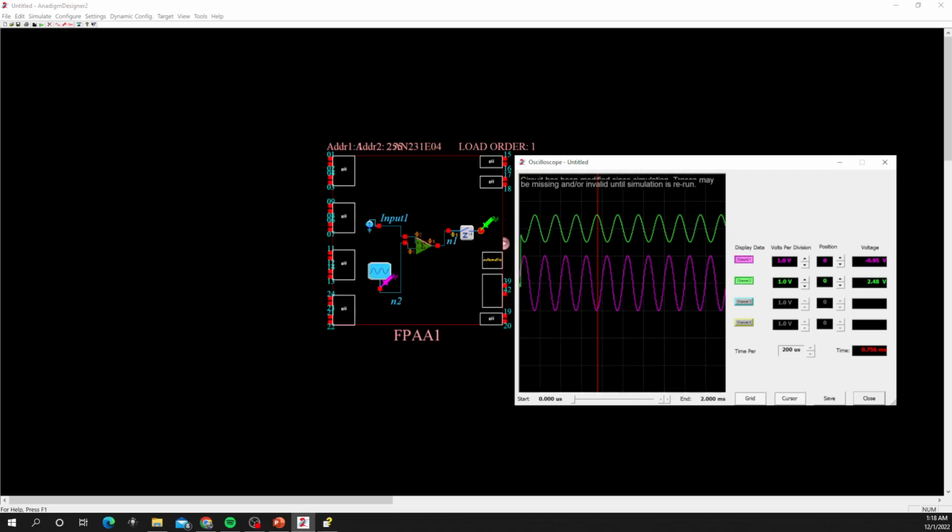And as we are also shifted by a DC bias, it is supposed to oscillate around 2 volts, right? As you can see, here it is close to 2 volts if you read it from the green color, this readout. And as we also use a non-inverting scaling factor, as you can see, they have a 180 degree or pi phase difference.